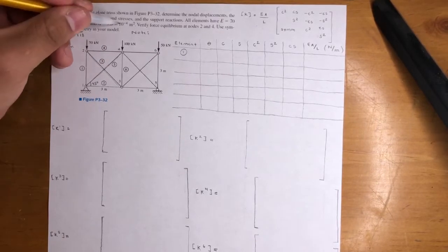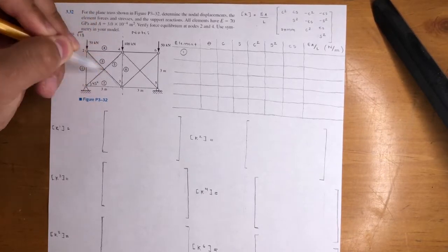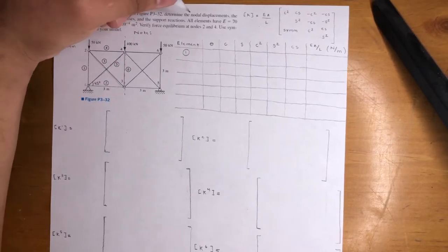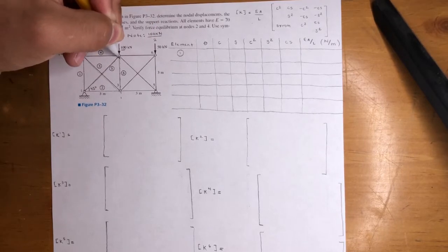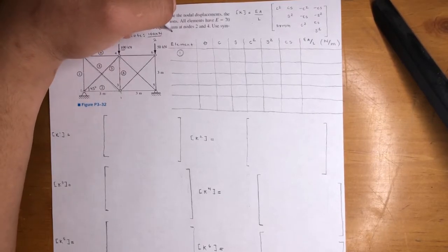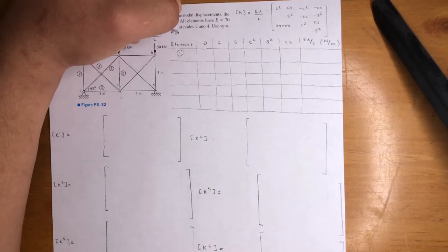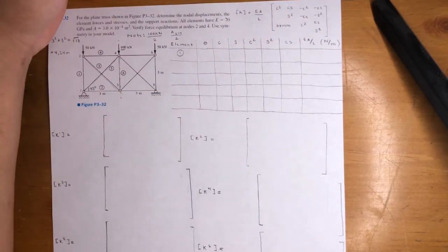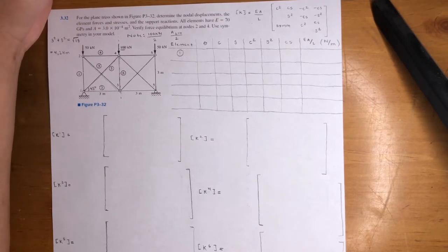So it's using symmetry, so we're gonna cut it down this way. The reason we do this is because it's all perfectly even. It's pretty straightforward. So what happens is this 100 kilonewtons gets cut into 2. Just keep that in mind. And the area of this bar gets cut into 2. So the area from nodes 3 to 4 gets cut into 2. So just keep that in mind when we do EA over L, when you start doing the verification of forces, all that good stuff. But for now, we just continue like we would otherwise.